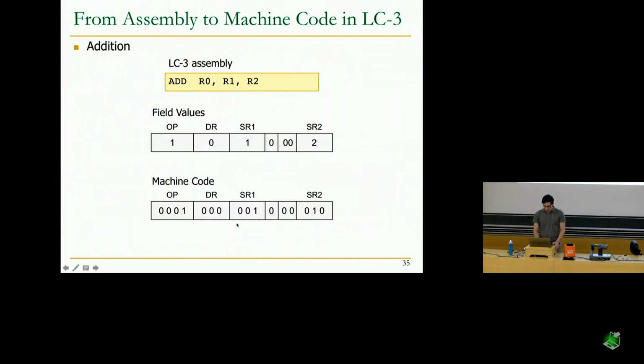So we need a way of representing all these 4 elements that you can see in the assembly, the mnemonic and the operands. That's why we need what is called instruction format or encoding. As you can see, we have 4 bits to represent the operation.